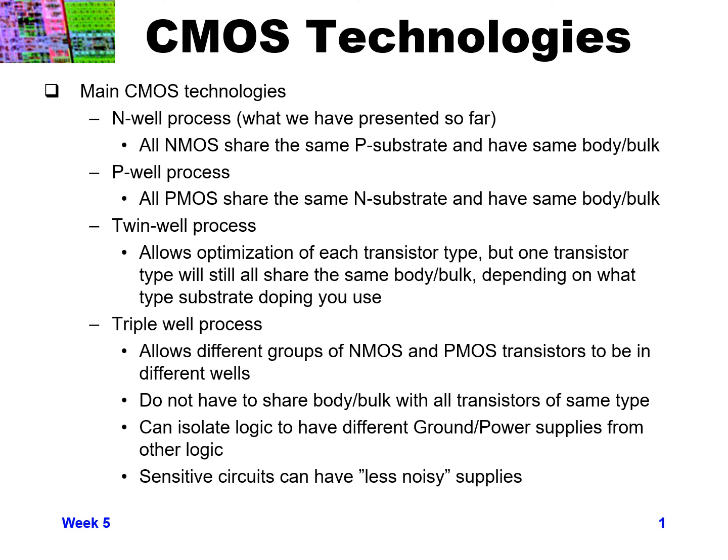So in this case, all PMOS devices would share the N substrate as their bulk/body, and their gates would be over that N substrate. In both of these cases, the devices that are not in the well, their gate structure is determined by the substrate doping.